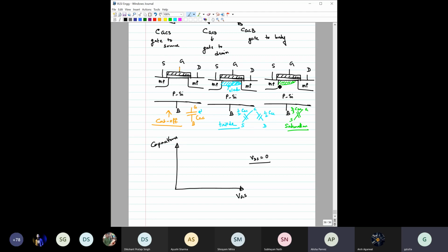Okay, so have you understood why it would be 0 for the second case? Right. You might think that there are some regions right here. But actually, we are saying the channel does not exist. But how do you define channel? There will always be some amount of electrons here, and those electrons will be sufficient to terminate the electric field which is coming.